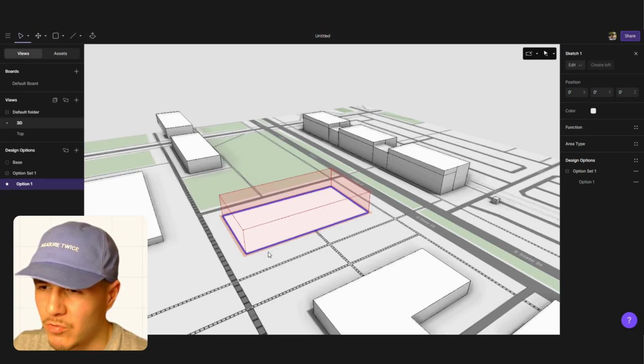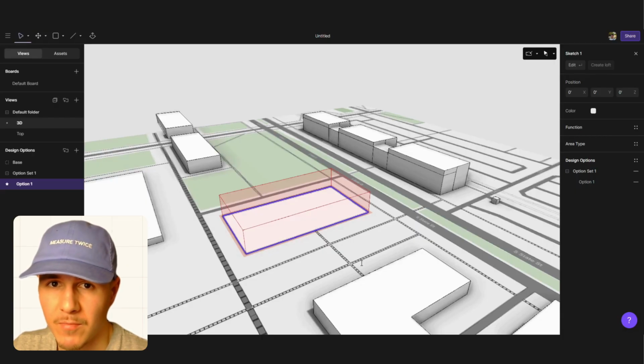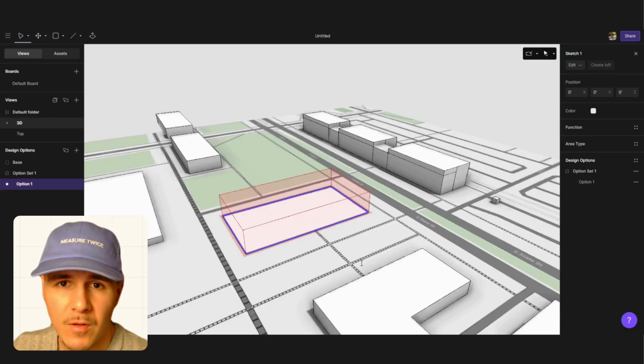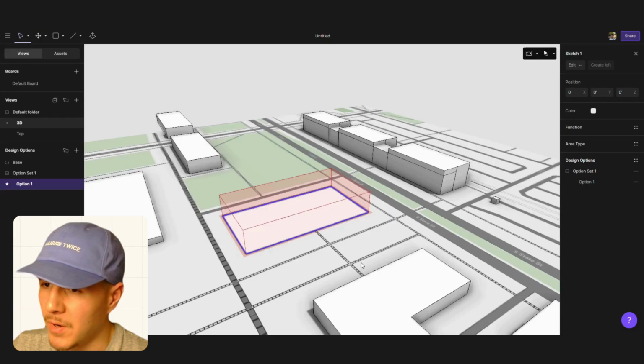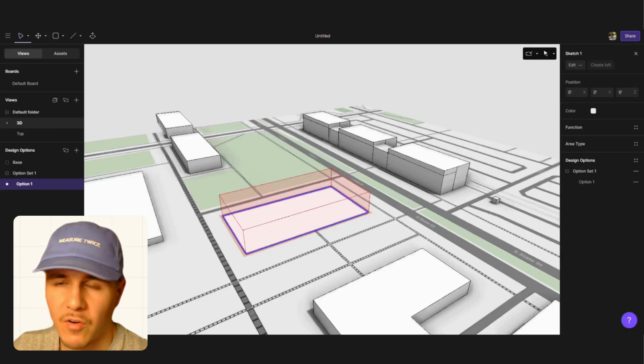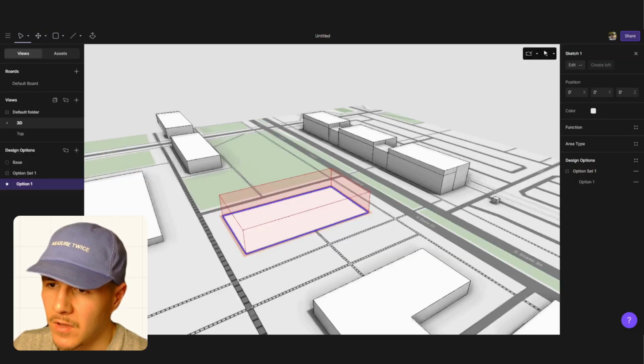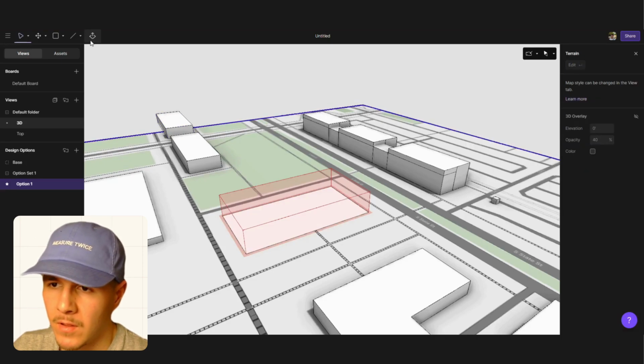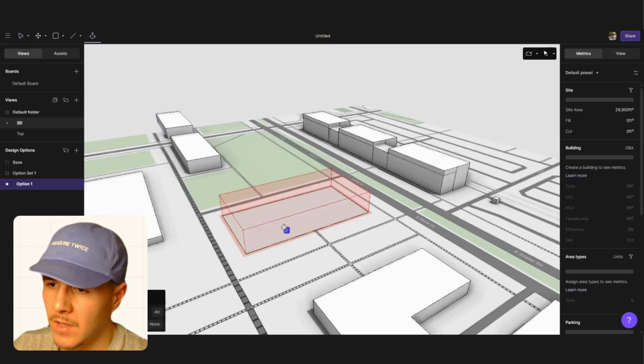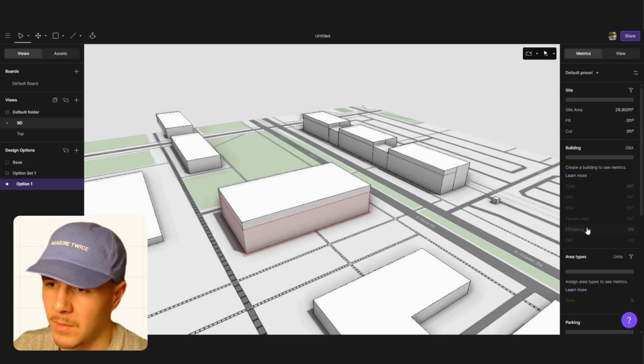What I just did was create the floor plate for my building. Just made a rectangle that's 220 by 120, and right now I'm just checking the floor plans to see what is the height of my different floors. Once I've checked that, I'm going to click the extrude button on the top left, and I'm just going to extrude the base plate to make a mass.